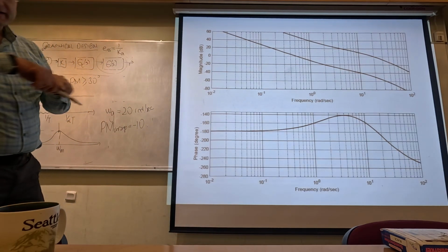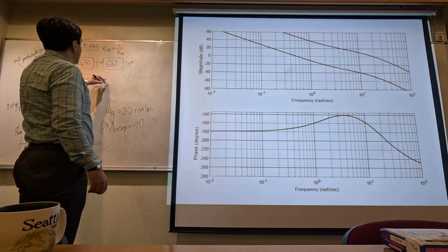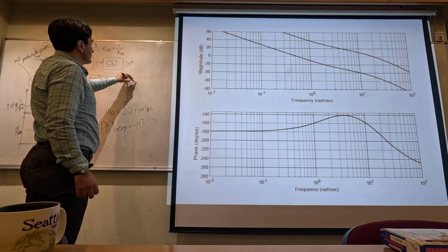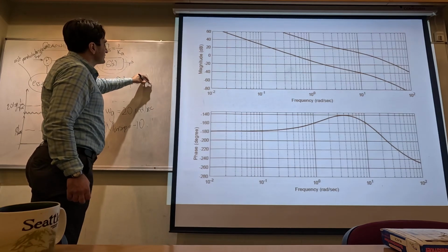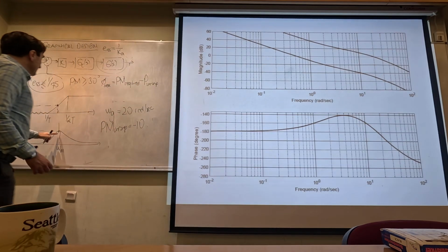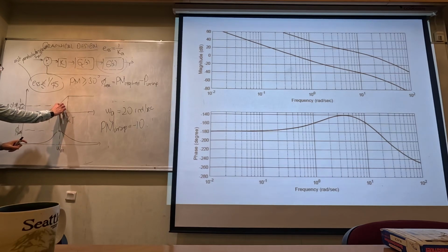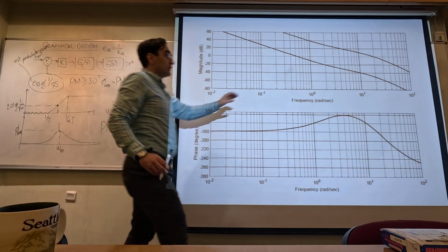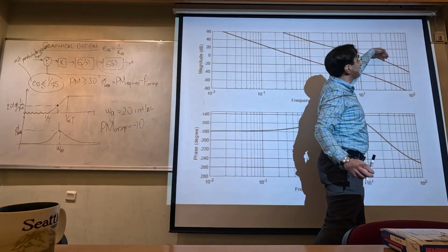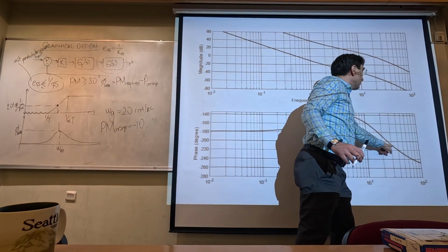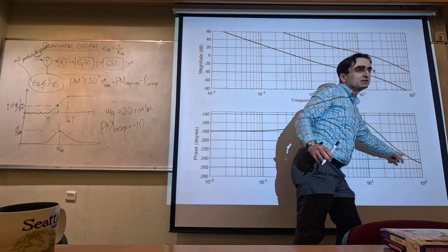Remember, we get that number as follows. I have phi max is equal to required phase margin, okay, minus uncompensated phase margin. Remember here, when I add this phase to the system, there is also a magnitude added to the system. This magnitude, actually positive magnitude, shifts this frequency to the right, unfortunately. And that causes a further decrease in the phase.